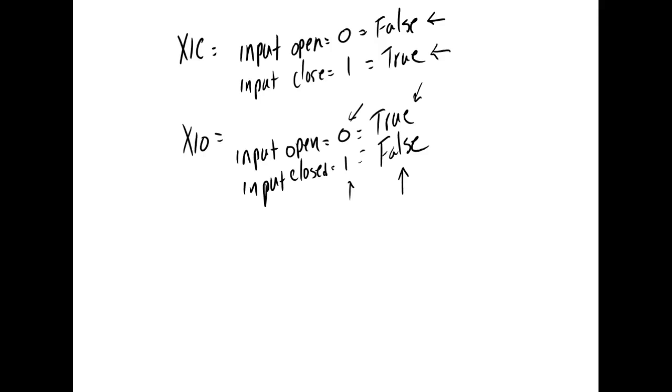This book has a pretty good section on sensors, and we do teach a sensor class. So normally open is going to default to examine close, and normally closed is going to default to examine open. Well, what do I mean by default? No, there are no defaults. The default is examine close. No matter what you put in there, it defaults to examine close. So how many of you ever went in there and changed that?